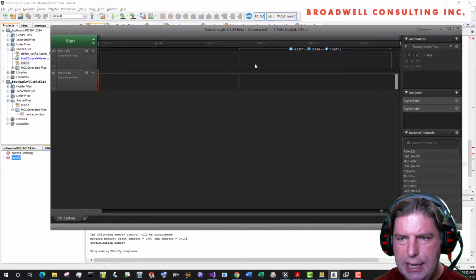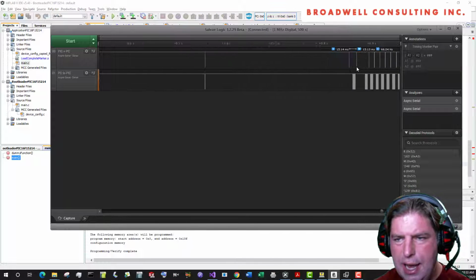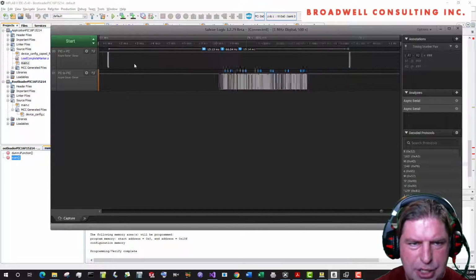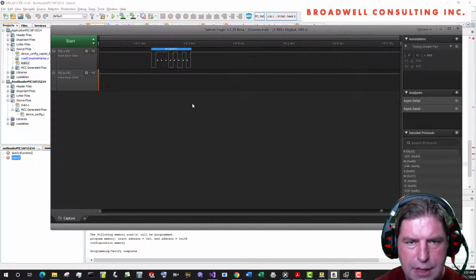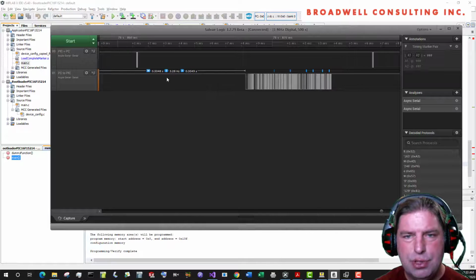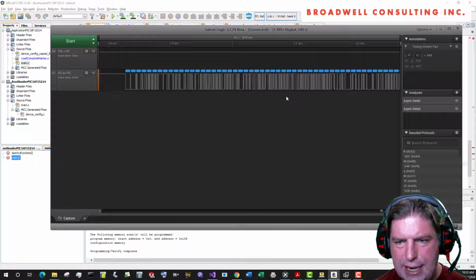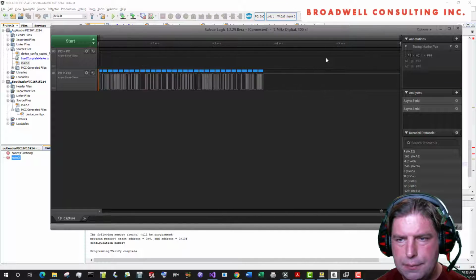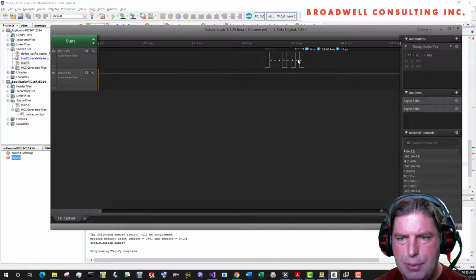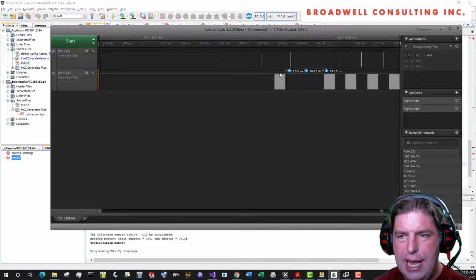And then at that point, we can see it takes about 300 milliseconds to do the erase, at which point it indicates back to the application that I'm ready to write. W, send me some data. Windows screws around for a few milliseconds, then sends it the first 64 bytes of data. The bootloader programs that in, sends another W saying I'm ready for the next word, the next line of words. And it continues like that.